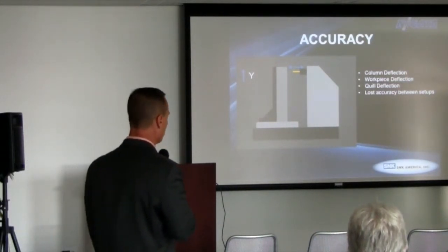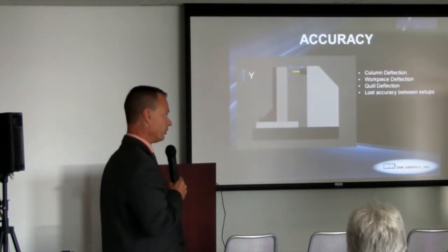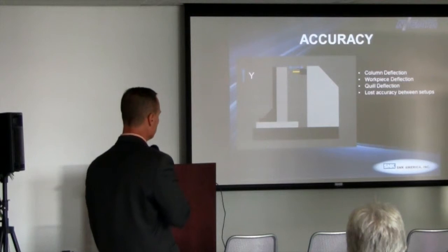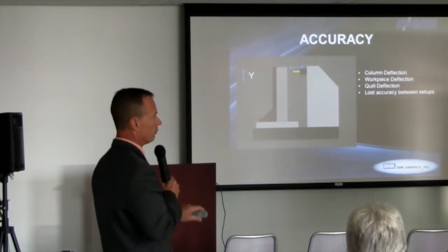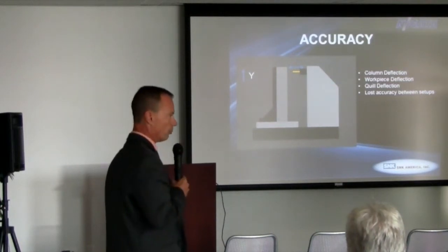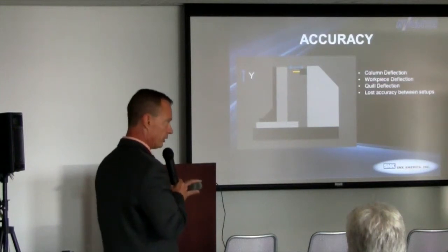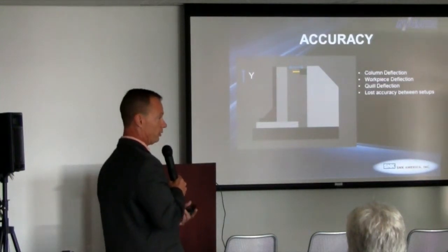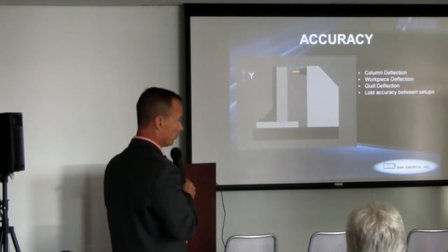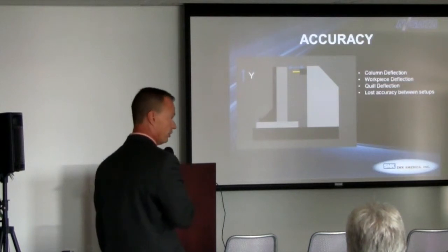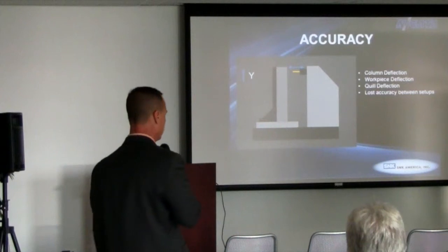The other thing that happens on a horizontal boring mill is that it's nice to have the capability to push your quill out to get extended reach. What happens when you do that, however, is you start to lose cutting capability the farther the spindle extends out. And this is true on every single boring mill ever made. Anything with a quill, the farther you are extended, you start to get two things happen. One is that you lose cutting capability. So the cutting capability starts to go down the farther you get extended. So you can't cut as heavy. Maybe you got to use a smaller tool. You got to take more passes. You got to baby the process a little bit more.